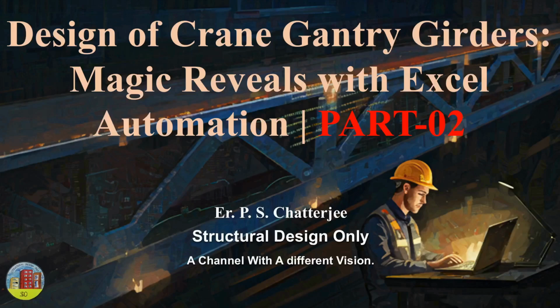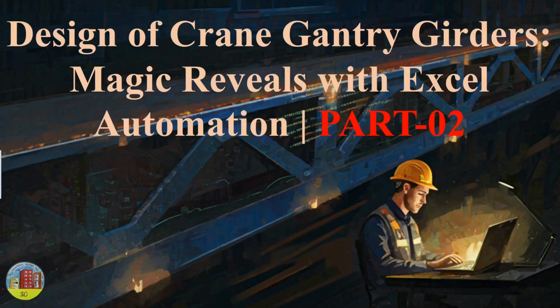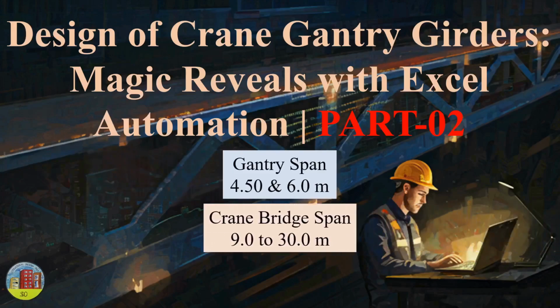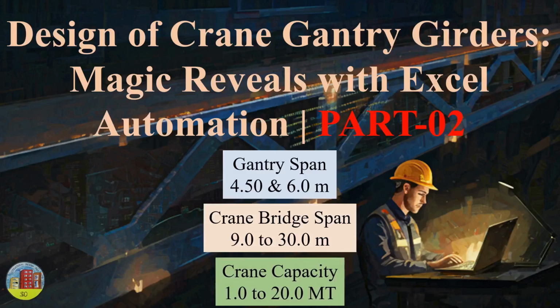In this session, we will focus on the practical application of Excel-based automation for gantry girder designs with base spans of 4.5 meters and 6 meters, and crane bridge spans ranging from 9 meters to 30 meters. We will cover crane lifting capacities from 1 metric ton, up to 20 metric tons. Along with the structural logic, we are going to use Excel VBA for seamless data refreshment and report transfers.